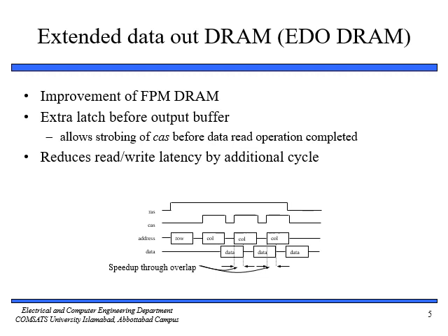Because of this, we can have a reduction in our read write latency, and we want our latency to become less so that we can have high throughput. So we can further reduce our latency. Let me take a pointer here. This is our RAS signal, because we just need one row, and then we have the CAS signal for three columns.